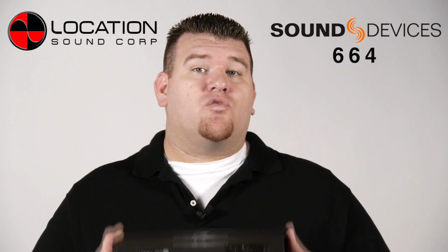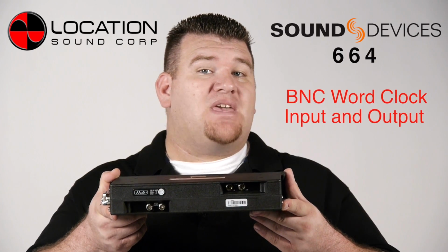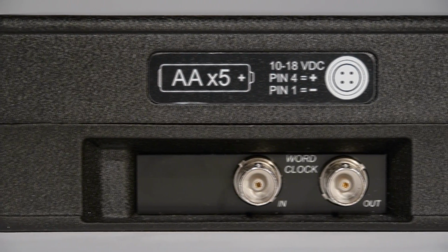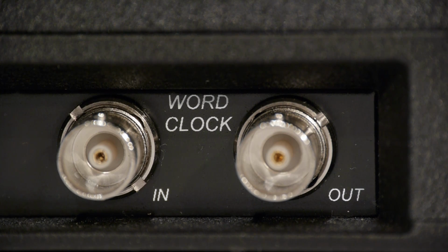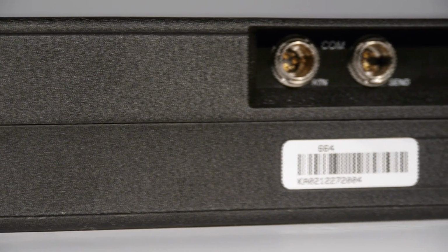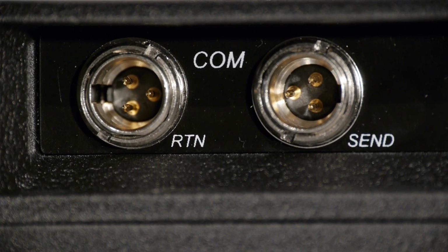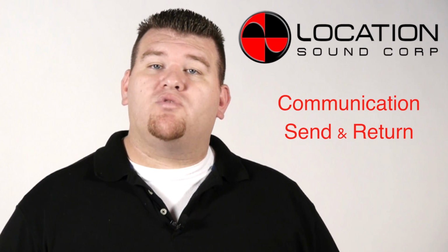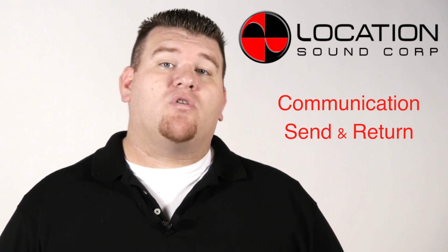In addition to that, on the rear panel of the 664, you'll find BNC word clock input and output, which can be used to clock the 664 from an external word clock signal or to synchronize external audio devices to the 664's word clock. Another valuable feature Sound Devices added on the 664 is its unbalanced stereo line level comm send and return for communication purposes. These special TA3 input and output channels can be used to privately communicate with a boom operator or other member of the production crew.